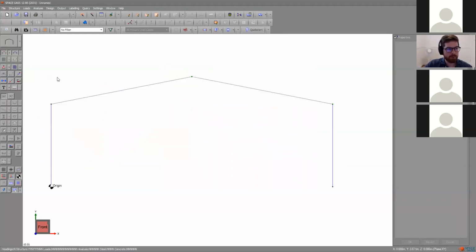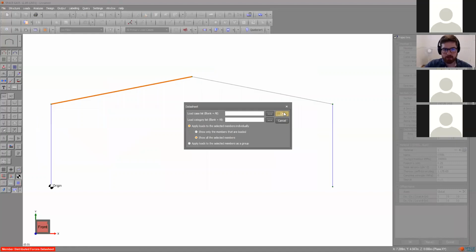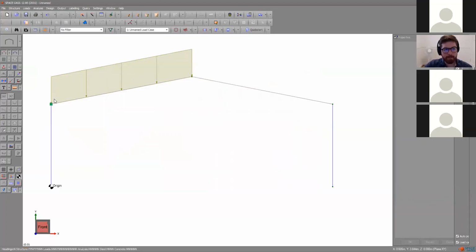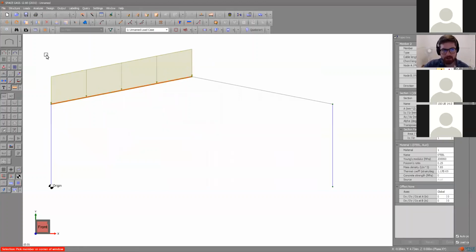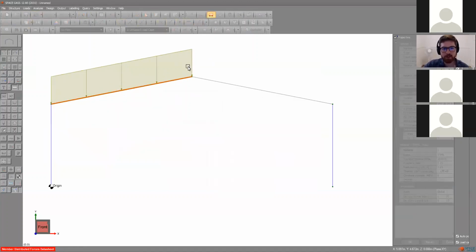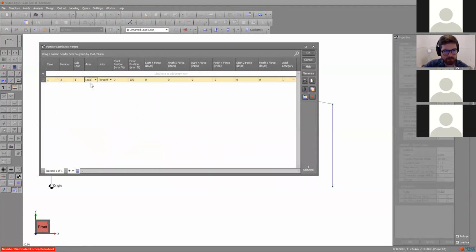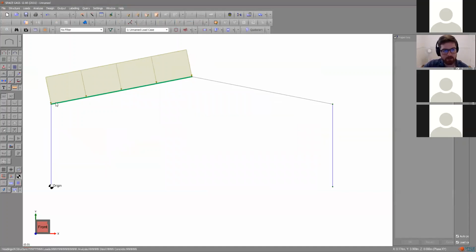The portal frame wizard. If I want to apply a member distributed load as a wind load for this portal frame element, okay, the global system points straight down, but a wind load needs to be perpendicular to the element. So I want that load to actually be in the element's local system, which allows me to actually have it as perpendicular to the roof.